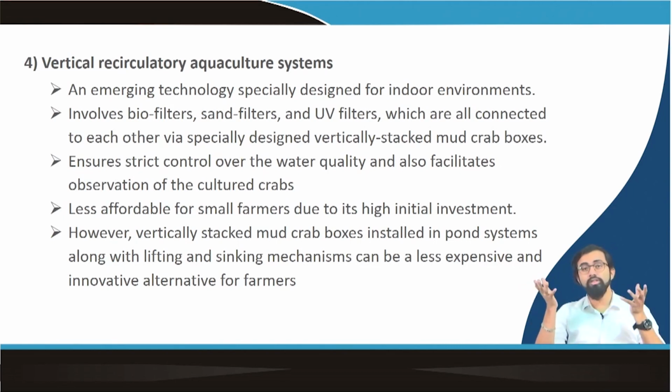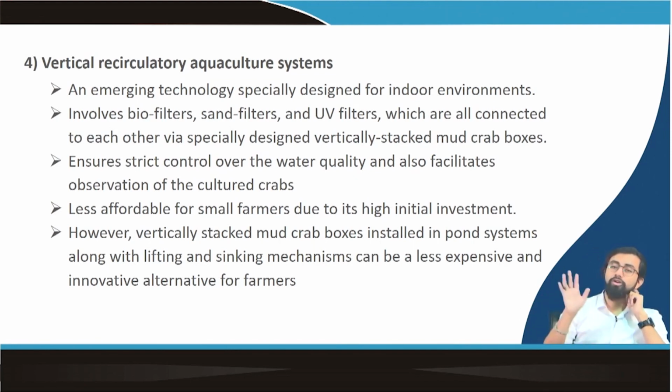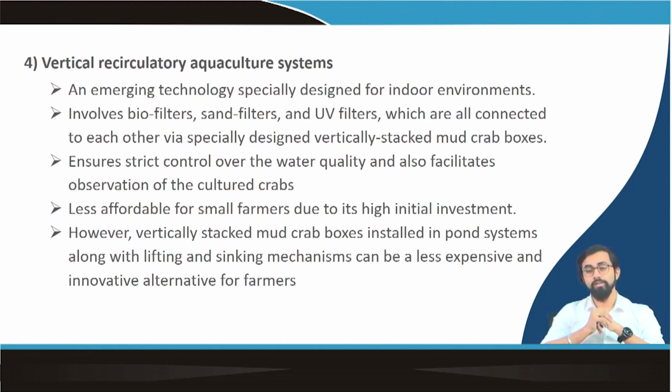And at the end, we go for a UV filter, it's just an example. Don't think it's only UV filters you need to use. You can use an ozonator and these things also. There are advanced oxidation techniques. There are a lot of technologies available in this field, which are mainly used to reduce the microbial content. What does that mean? It will reduce the pathogenic microorganism content in the water.